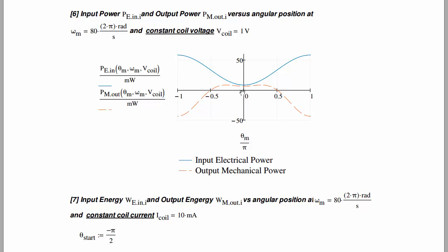And what we note here is that the output power, the amount of power that is delivered to the mechanical side of the motor to overcome any friction, accelerate it by delivering more energy to be stored in the rotational inertia, or to be delivered to some mechanical load that's connected to the output of the motor shaft, is going to be supplied by the orange dotted line here.